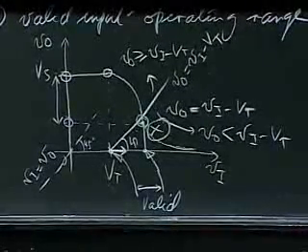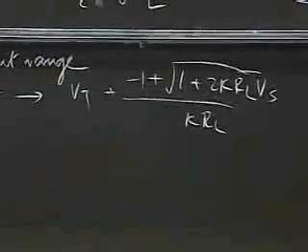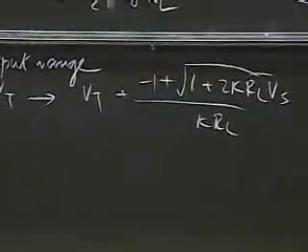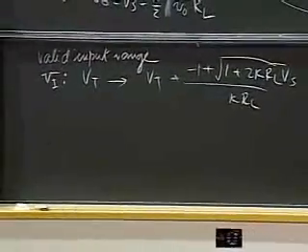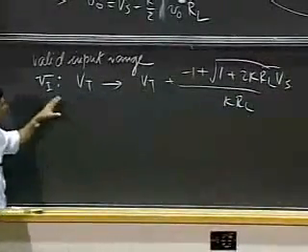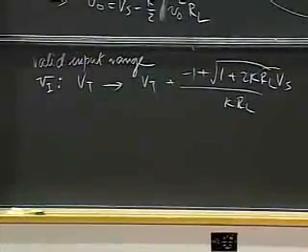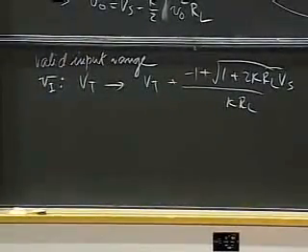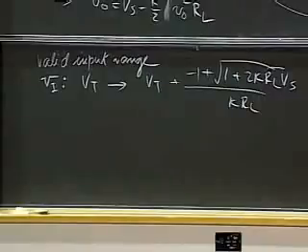So now as an engineer, I can say that if you build a MOSFET circuit like so, with a given value of RL, a given MOSFET, and a given Vs, then if you limit yourself to operating with input voltages in this range, thou shalt be happy. If you go beyond that range, then you will be violating the saturation discipline.